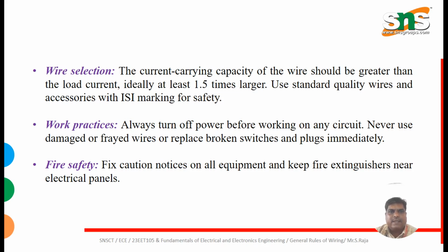Work practices: always turn off power before working on any circuit. Never use damaged or frayed wires, and replace broken switches and plugs immediately. Fire safety: fix caution notices on all equipment and keep a fire extinguisher near electrical panels. These are the main areas that need to be maintained if you are going to any public places or any workshop where electrical circuits are used.